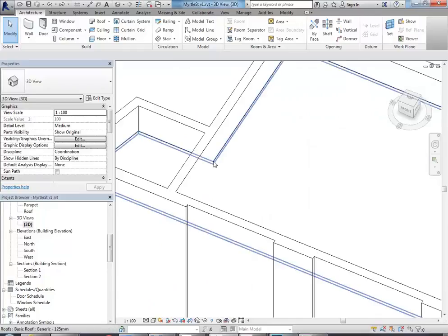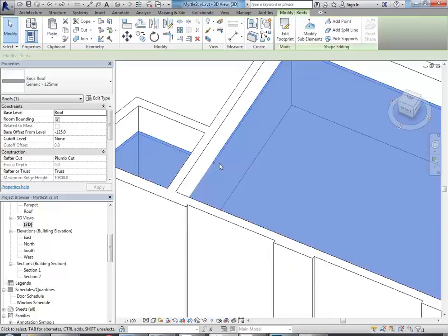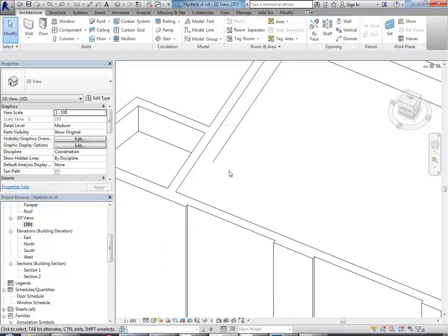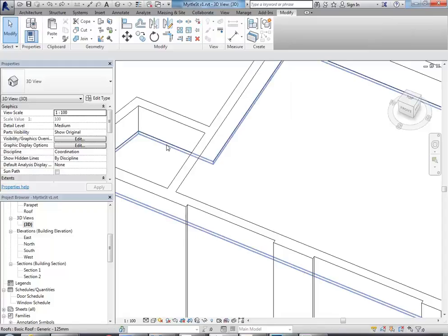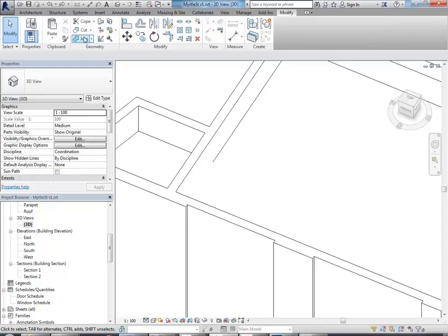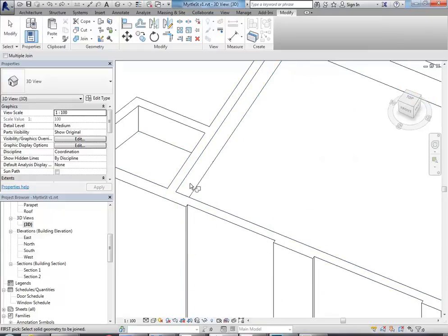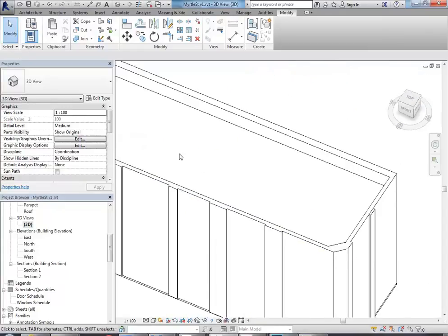and maybe just very last thing there, you can see there the roof does the same thing as the floor. So it's a nice thing when it asks you if it wants you to, or if you want the program to automatically join and cut that overlapping volume out. It really does save you a lot of time, but for some reason it just doesn't always ask you that, so you just have to get used to going around and joining things using the join tool manually to clean things up. And you'll see it happen everywhere.